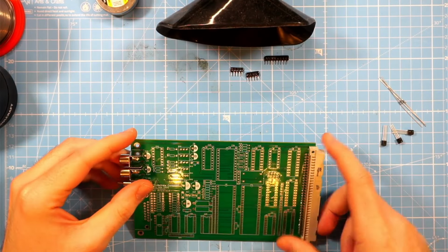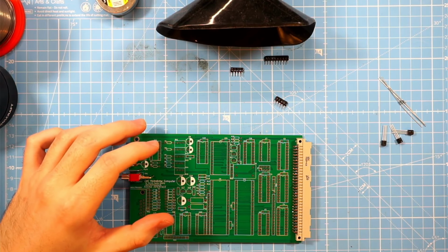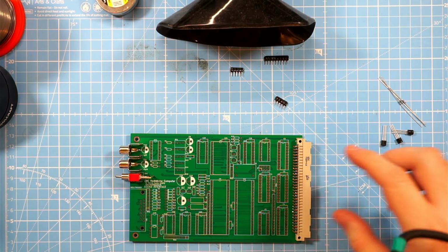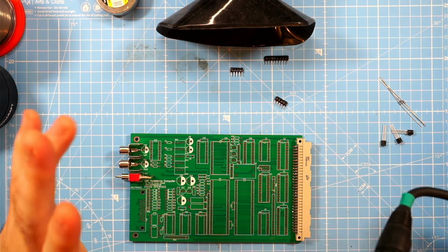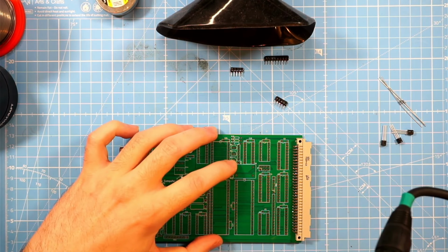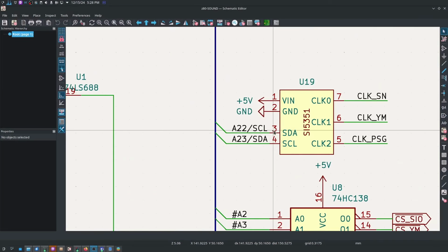Let's get started. That's actually the part that I'm least looking forward to. It's quite a lot of work. Yeah, let's see how this turns out. So first of all, one thing that I needed to check was the orientation of the pin layout right here, because as I've shown you earlier, I think that I made an error right here. Pin 3 is SDA, but it's actually wired to SCL, and 4 is SCL, which is actually wired to SDA.